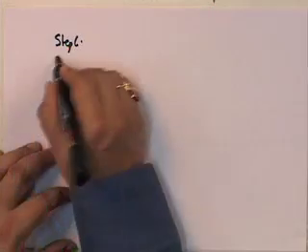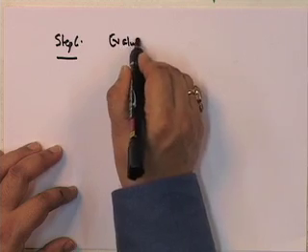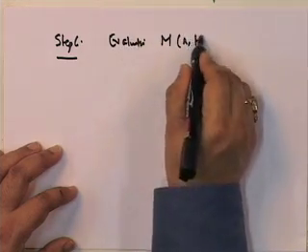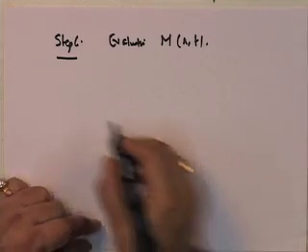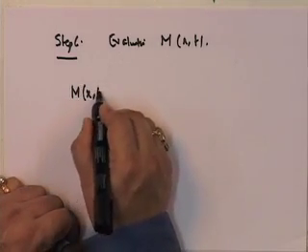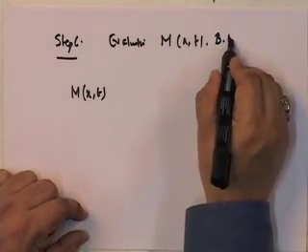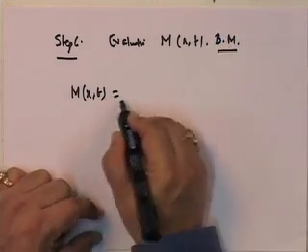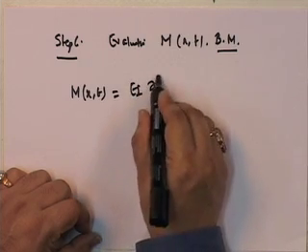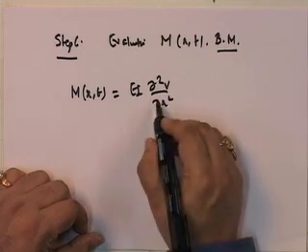Now we've got the displacement response. So now let's look at the force response. Let me look at bending moment. So this was step 5, now step 6. Evaluate mx of t. What is mx of t? Bending moment at any instant is equal to EI del squared V by del x squared.